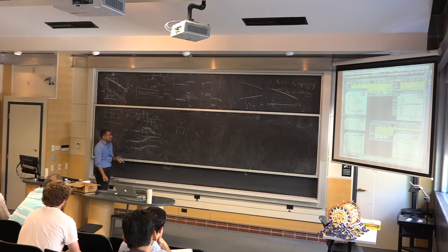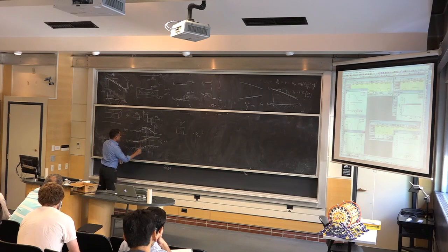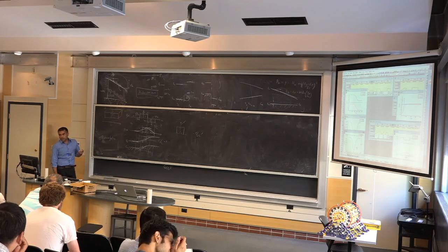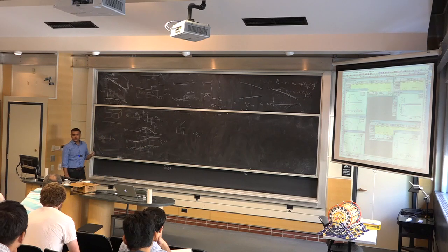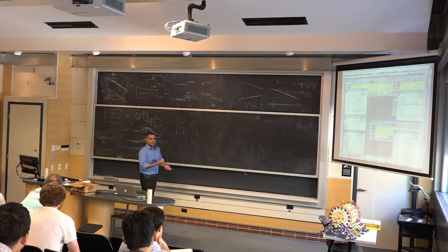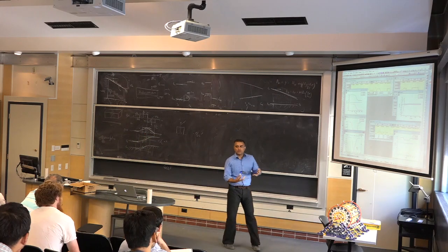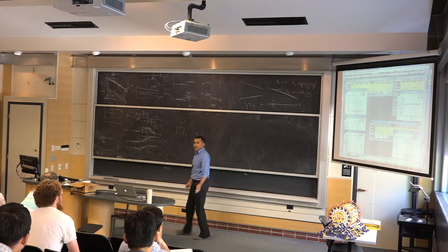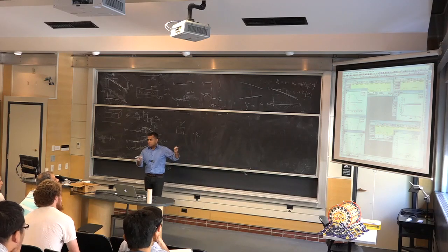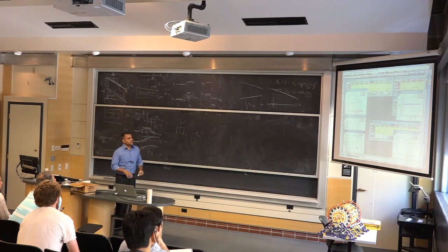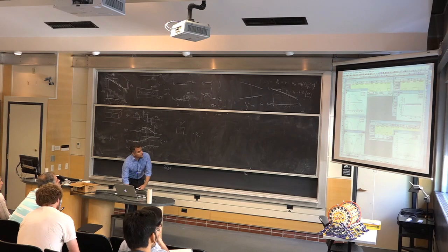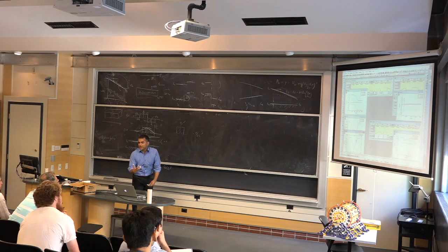Put a quantum well. Now, the Poisson equation doesn't know anything about quantum mechanics. Poisson is classical physics, right? So you need to solve Schrodinger in parallel with the Poisson equation. This is a self-consistent Schrodinger-Poisson solver, and that's what this program does. It solves both Schrodinger and Poisson self-consistently, and as a result, it gives you details that are consistent with quantum mechanics at the same time.